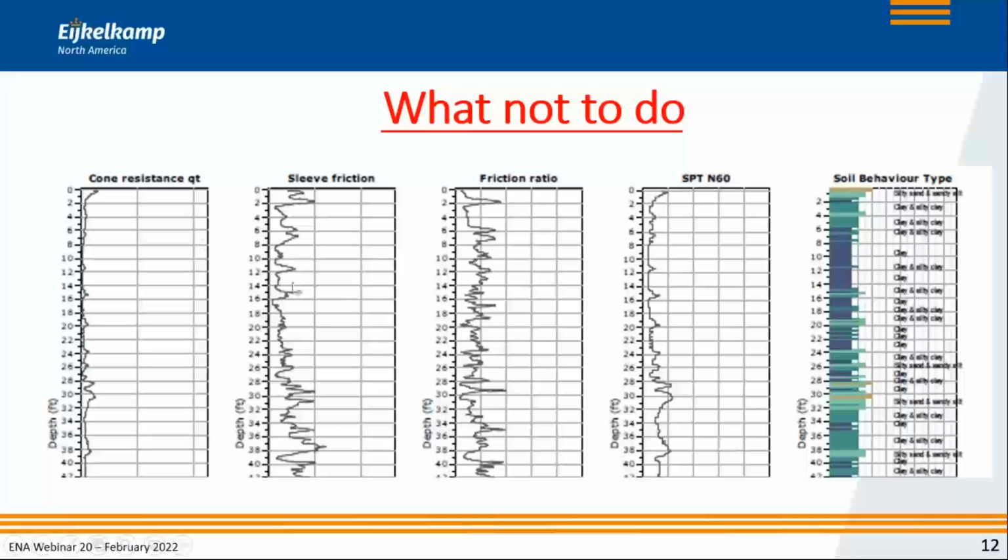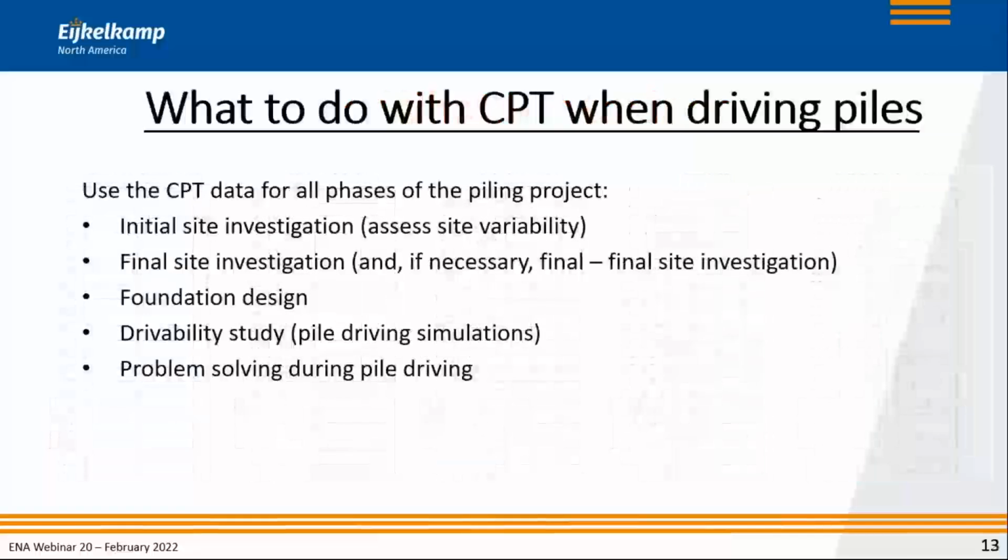They say, well, you do your CPT because my boss wants you to do CPT or my client wants you to do CPT, but please use some kind of correlation to convert those data back to an N60 value, because then I know what to do. And of course, in the end, if that's what the client wants, that is what we will give the client. But please don't do that. Don't just go back. Use the CPT data directly for all phases of the project, as I will show you, at least to give you an indication of the flavor during the remainder of this presentation.